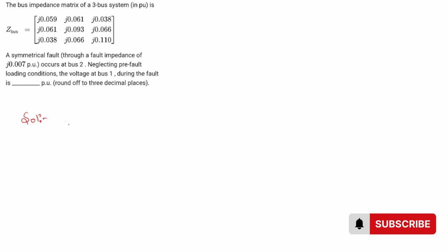Z bus is given. The question asks that, neglecting pre-fault load condition, the voltage at bus 1 during the fault. So he asked about V1. What is given? ZF is j0.07 per unit, and the pre-fault voltage is equal to 1 per unit. Neglecting pre-fault load condition, we can assume V pre-fault is 1 per unit.